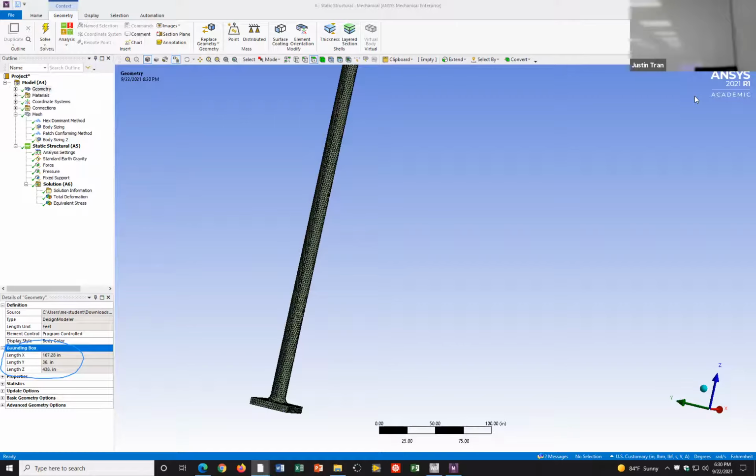Deformation. Whole body, right? So that basically is a number that multiplies the size of the element. Refinement of 1 basically means it's like 1 plus the refinement. And so refinement of 1 means that the elements are going to be twice as small, and refinement of 2 is 3 times smaller. Refinement of 3 is 4 times smaller.